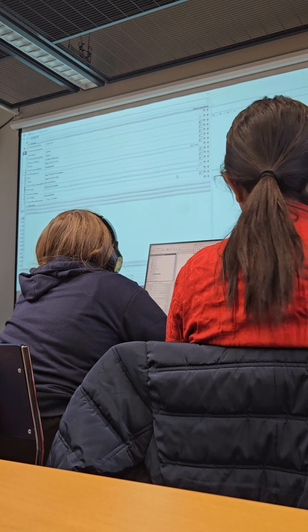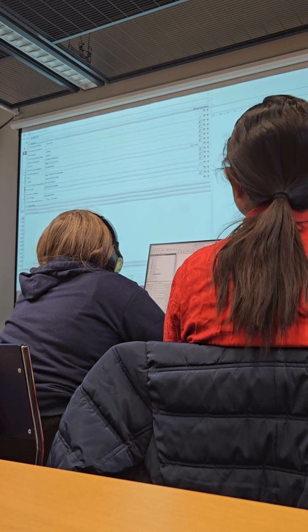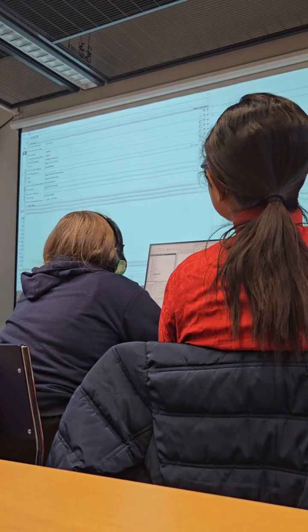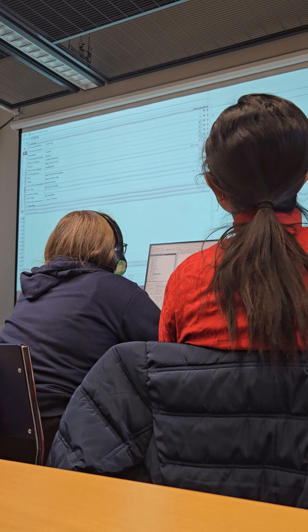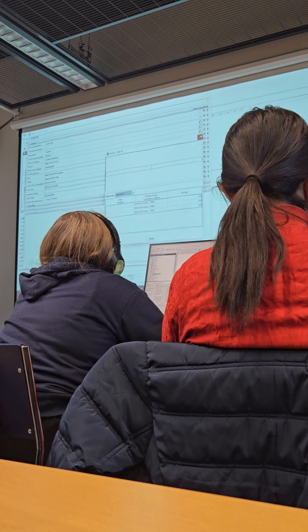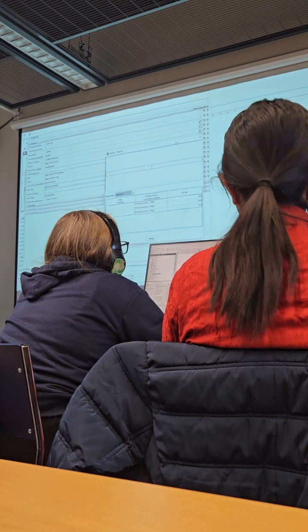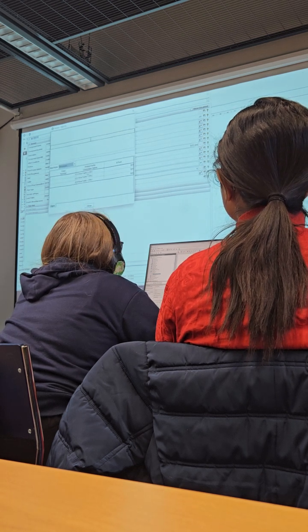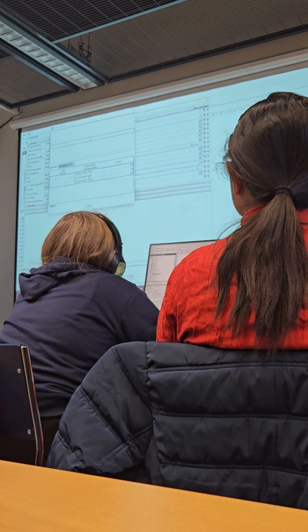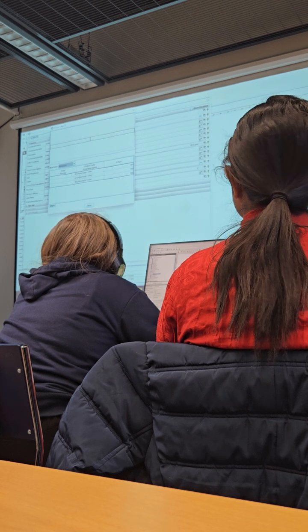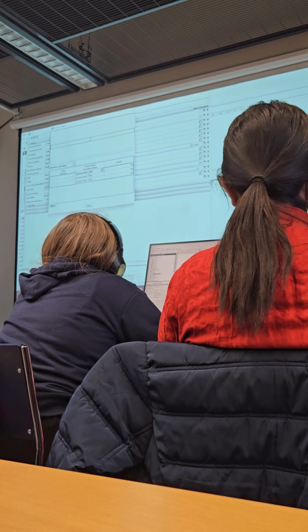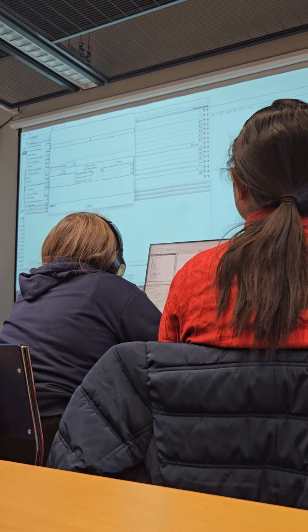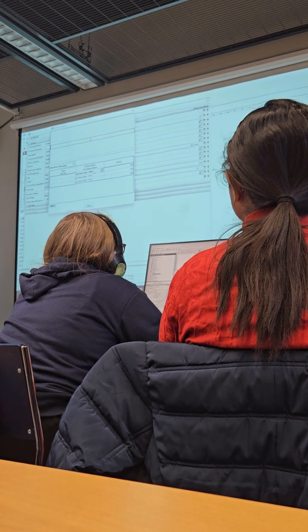So if I double click that component, then I can find the friction parameter here, and we can get this kind of view which tells now what kind of friction options it uses by default. And we can see that there's a flow factor plus friction, but in this case it's not enough because there is this abrupt area change taking place.